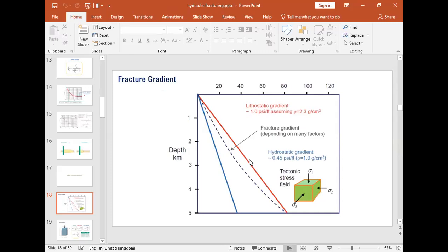It means you have to do an analysis to ensure that the mud injected inside our borehole has a pressure greater than our pore pressure, so that it stops formation fluid from getting into the borehole and causing a kick. A kick means the uncontrolled flow of hydrocarbon fluid during our drilling process.